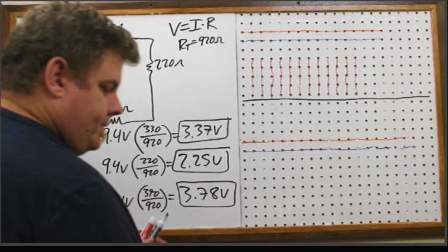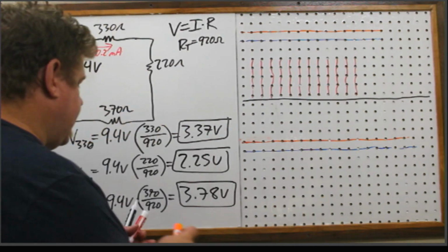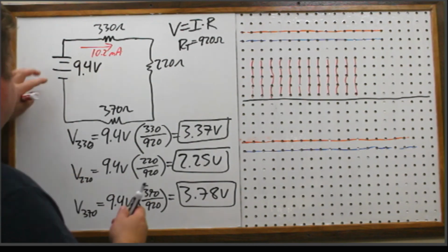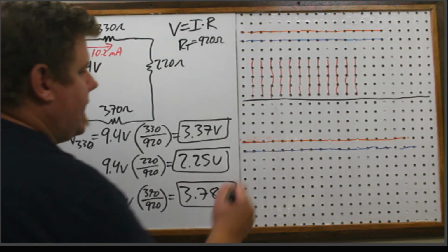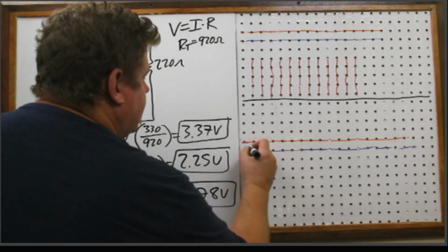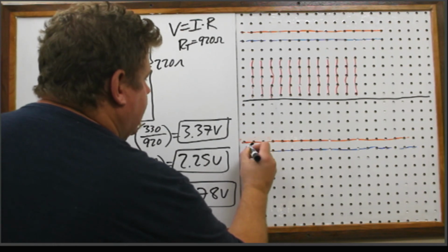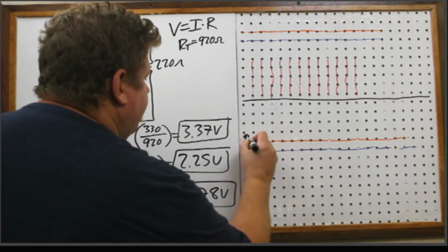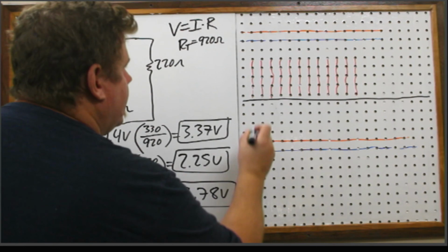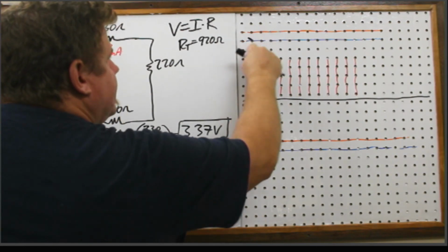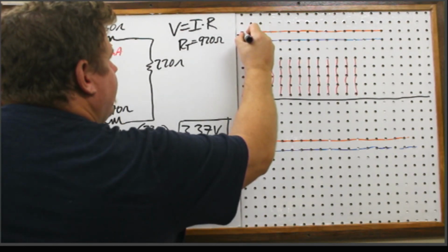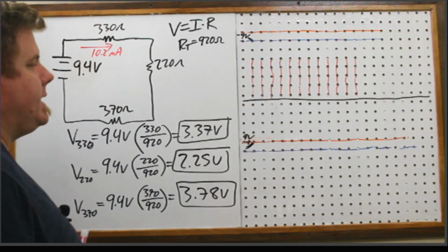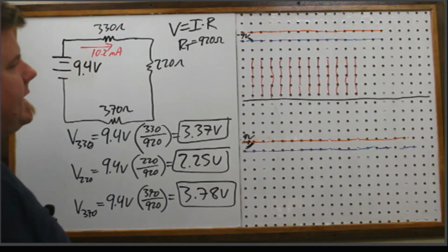Okay. So I'm probably going to come in with my 2 leads for my power supply. Let's say that I put the positive lead in here. So this is 9 volts positive. And then right here on this line, I put the negative side of the battery. Okay? So there's my 9 volts and there's my 9 volts.